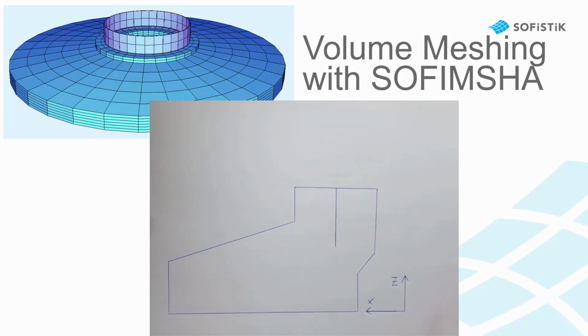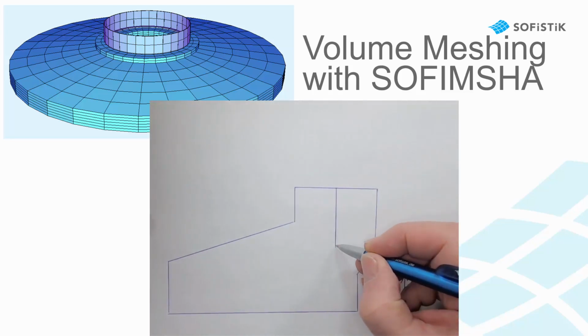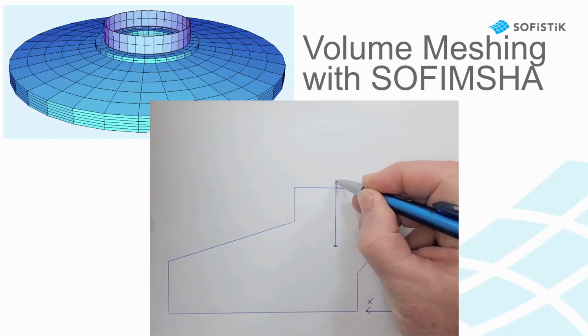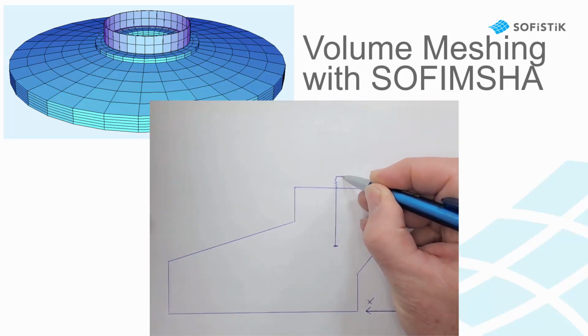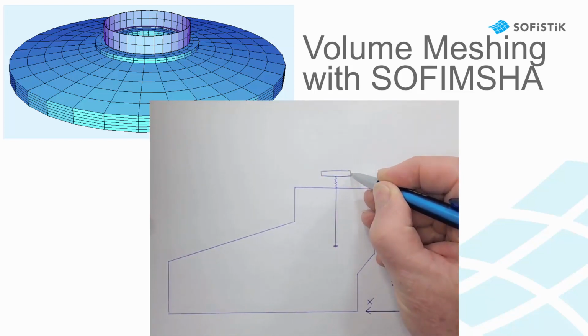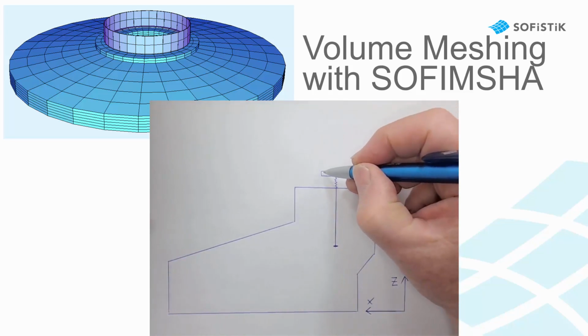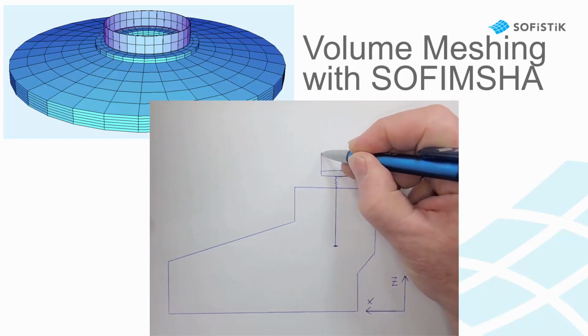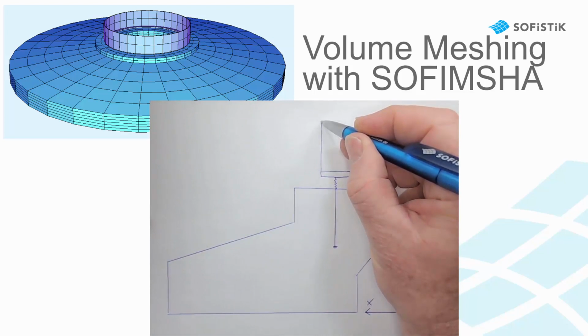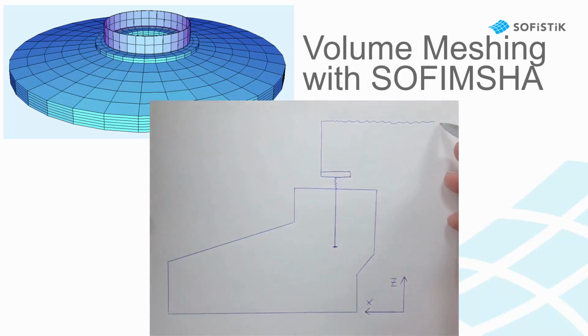When we start, it is always a good idea to make a sketch on a sheet of paper. We have here our concrete, here the bolts for the tower. We have a connection spring that connects the steel plate that we have here with the foundation. And this steel plate is a part of the tower ring. Then we connect the tower to a central node number 1, where we apply all our loads.